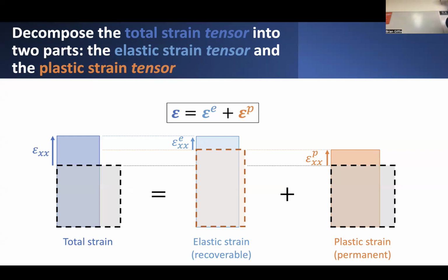So really, you're saying, treat the new reference configuration of the material, in other words, the configuration of the material in which a state of zero stress will occur, as the configuration in which you have plastic strains looking like this, which have permanently changed the zero stress configuration of the material.